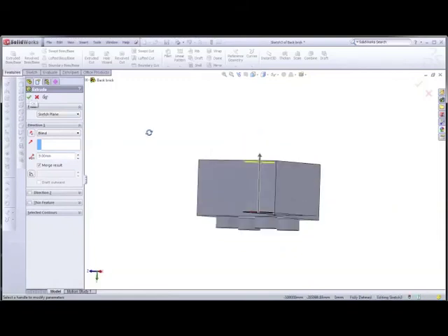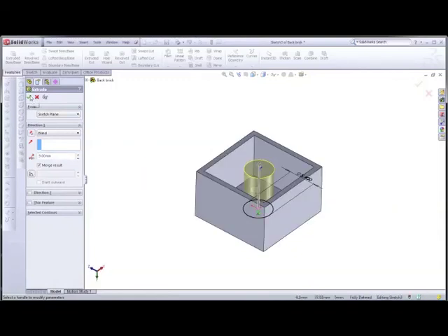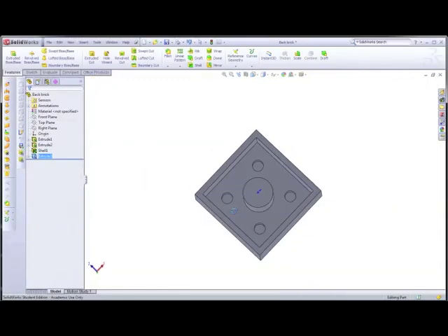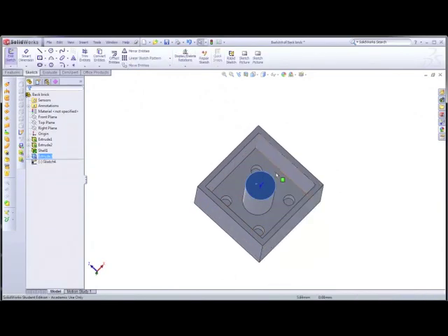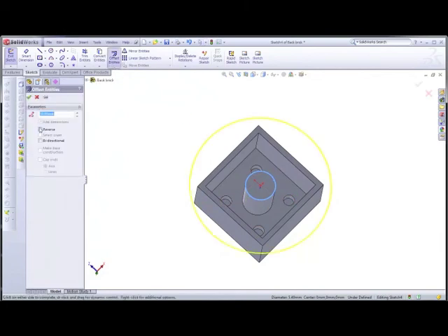So that's flat there, and I'll green tick that. Yep. Now, as you can notice, it hasn't got a hole in the middle, so what we can do now is create a sketch on this top plane here. Sketch, then we can click on here and go offset, select that line on the outside, offset, reverse direction, and then select 1 mil.